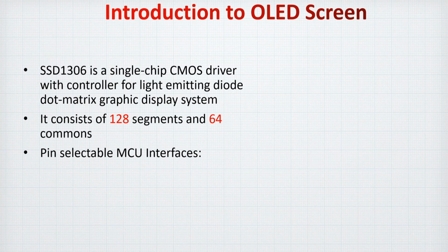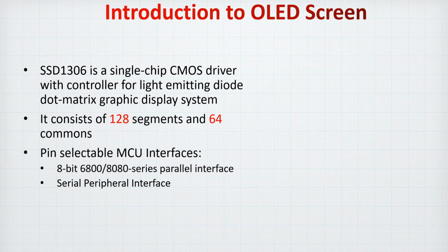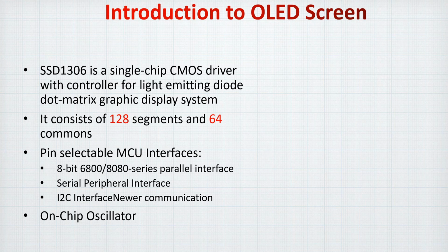This means that you can find some of the same OLED displays with this chip, the SSD1306, with an 8-bit 6800 or 8080 series interface. You can also find an SPI interface with this one too, and also an I2C interface. Finally, it has an internal on-chip oscillator.